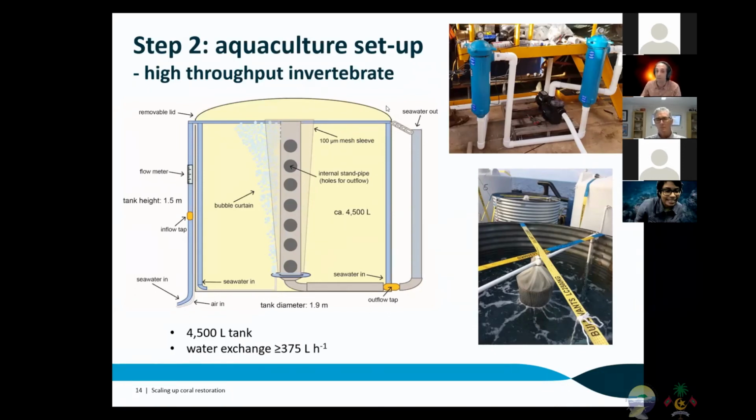That's great, thanks. So just going into that setup, we just use a pretty typical aquaculture setup, which is a high throughput approach for invertebrate larvae. We had constant flow-through water that came through two-stage filters of about 50 micron and then 5 microns. Before going into the tanks, it also went through a large UV filter. The flow was such that each tank turned around 2 times per day at a minimum. And the tanks that we used were rainwater tanks.